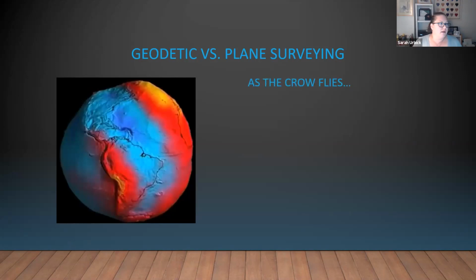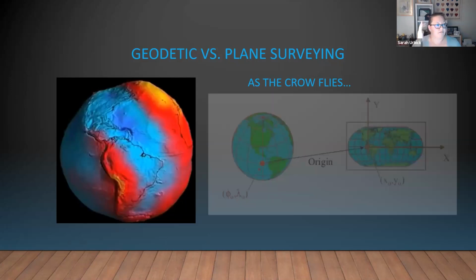So one thing you'll hear periodically, I don't know if you've heard it before, is "as the crow flies." So apparently, in addition to learning people's faces and having groups of them being called a murder, which is fascinating, as the crow flies means obstructions are not an issue. Variations in terrain are not an issue. They don't have to go to the corner, stop at the stop sign, and then turn left. A crow is going to fly in a straight line from point A to point B. That's what we do when we talk about plane surveys. We don't look at that variation.